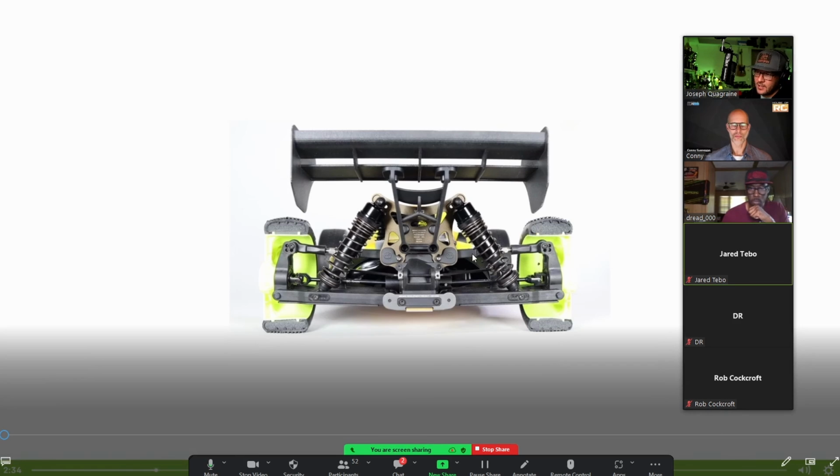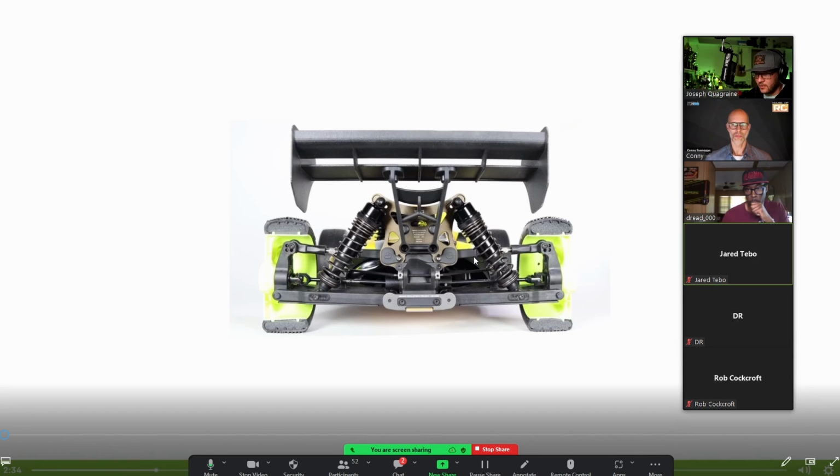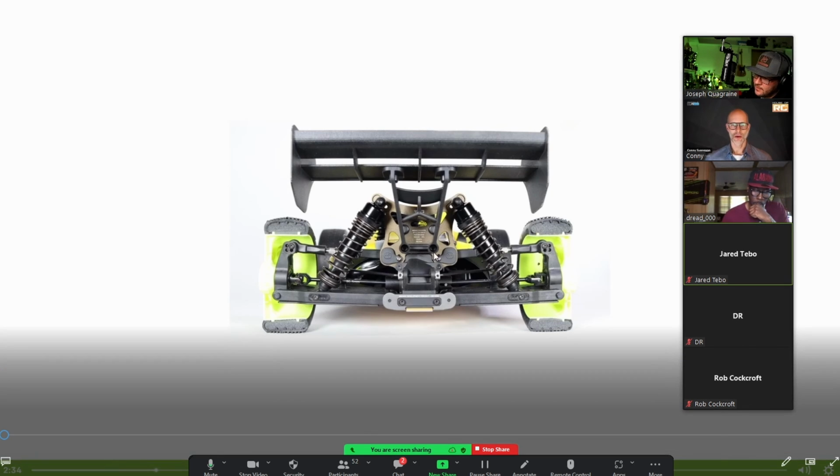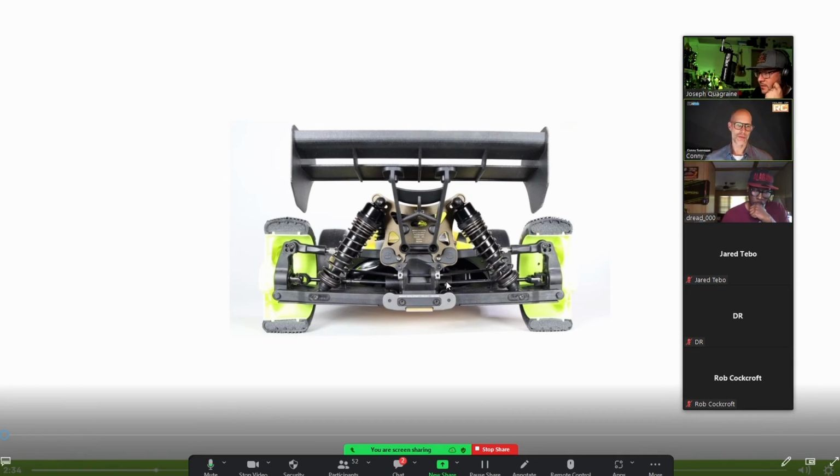By lowering that entire rear link, for example, going into a corner, you have good initial grip, the rear grips well, but then mid-corner, the low link allows the rear to break loose a bit to help the car rotate around the corner. Then when you get on power, the rear locks up again because of initial grip and stops sliding and accelerates straight. So yeah, that's my best explanation of that.